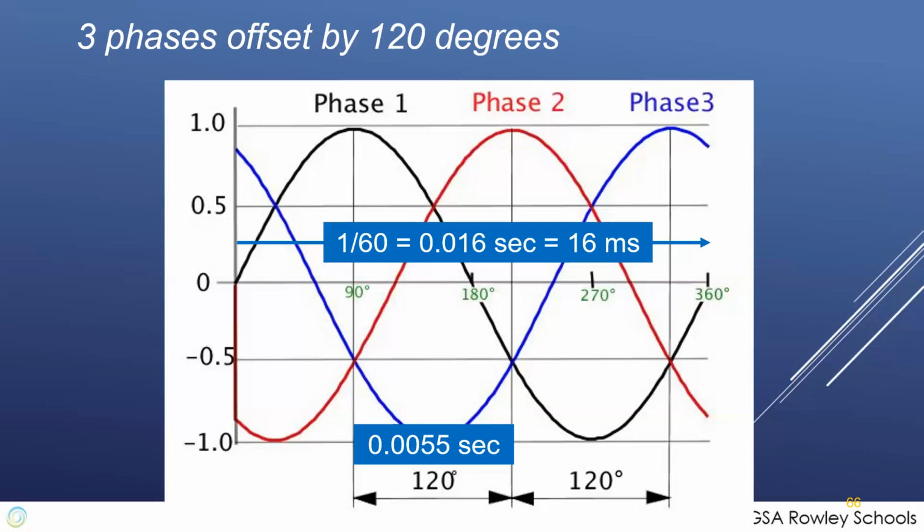Right. But the peak to peak time, they're 120 degrees apart from each other. So, I didn't draw it all on here, but the zero crossing of A here to the zero crossing of B here is 120 degrees. Yeah, sorry, I misunderstood the pictures, but thanks for the explanation. Sure. Good question.